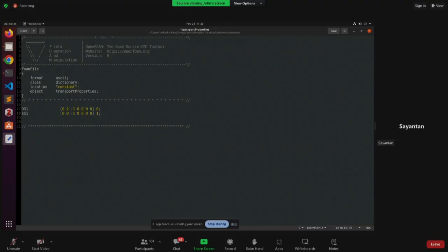Okay. Yes, John. I have one doubt. Yes. So if the equation is d phi by dt is equal to a constant term on the right hand side, but the code you have shown, the dot C code, there was ddt term, there was divergence term, Laplacian also. Yes, correct. So the equation will not change accordingly? No, we are not changing. So that's the beauty. We are not changing those equations, right? The main equation remains the same. If I give DS1, that is my diffusion, to be 0, right? Already that term becomes 0. Did you understand? So we are giving diffusion as 0. We are giving inputs. So if you put diffusion as 0, that whole term drops off, right?